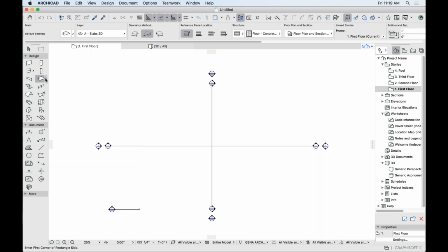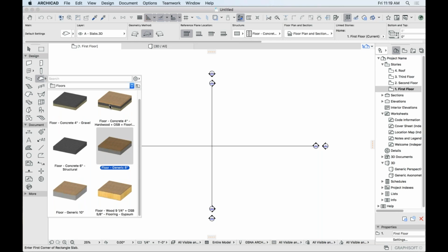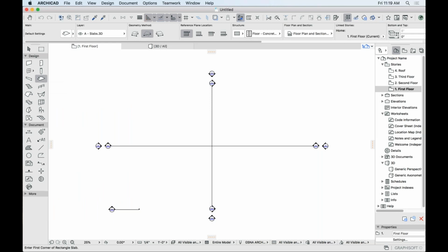So you just need to click the little arrow just to the right edge of the icon here, and that will pull out this favorites palette. Then you just double click an element, and that becomes the active style. Style of the active favorite is the technical term, but it will use whatever you see here and those parameters. We'll get into that a little bit just as well.